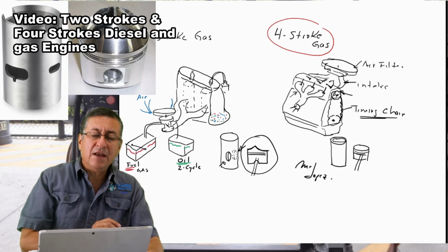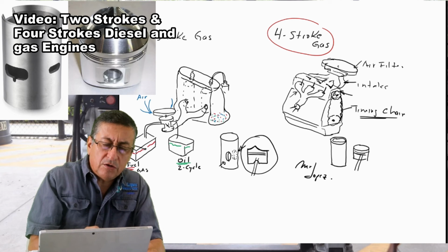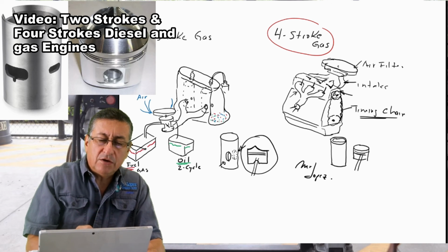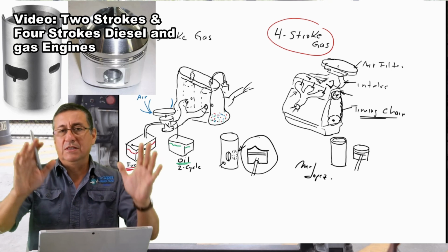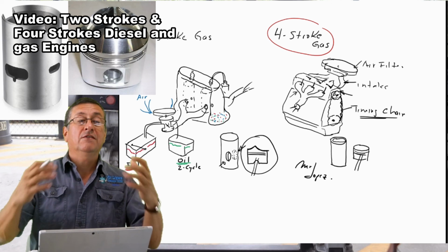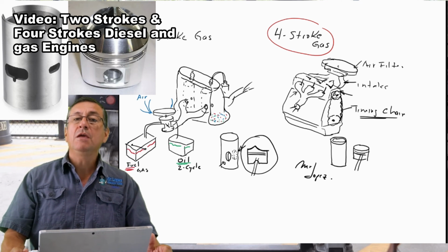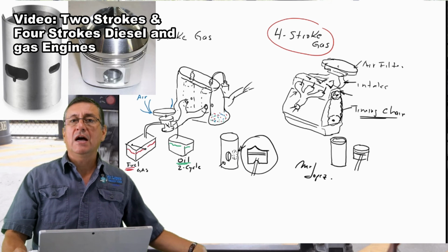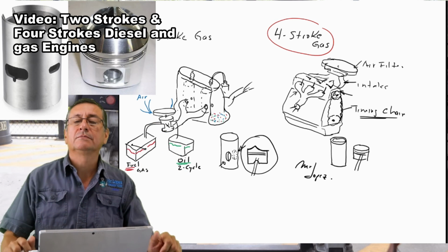And what is the idea? At the bottom of the cylinder, there are the holes, one hole here and another hole on the other side for exhaust, because the exhaust manifold is located here on the other side. Yeah, one of the differences, if you check by visual inspection, is that the 2-stroke engines have the input of the mixture and the output of the gases at the bottom of the block, not on top.